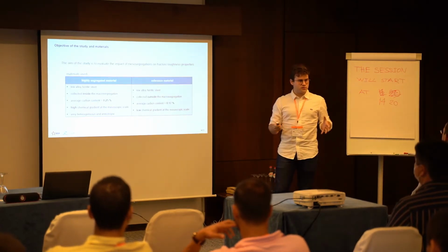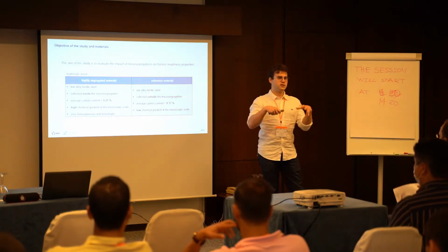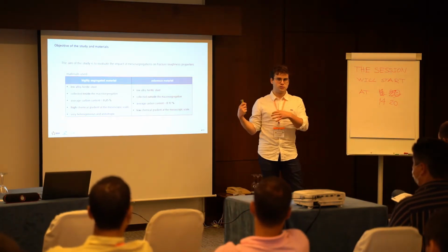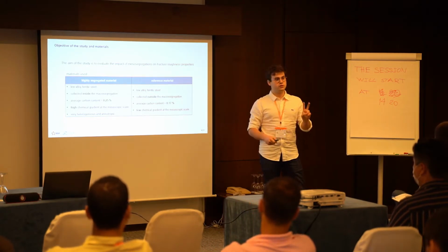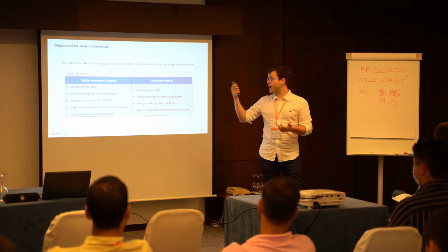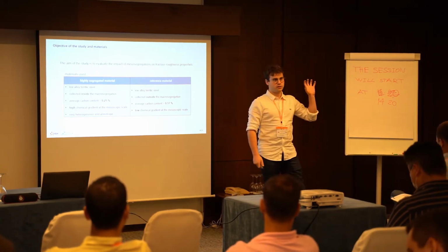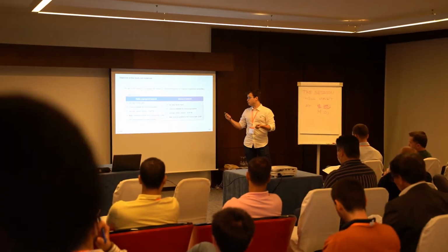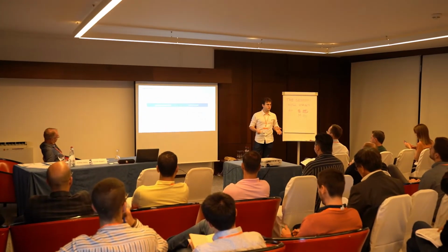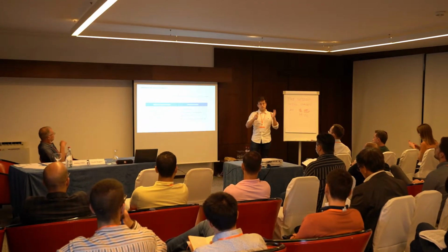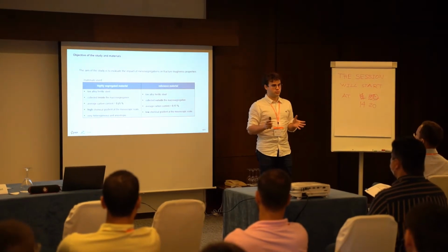So, the aim of this study is to evaluate the effect of those chemical heterogeneities, the meso-segregations, on the fracture toughness properties. For that, we used two different materials. One is highly segregated, collected inside the macro-segregation. Thus, it has a relatively high carbon content, on average 0.25%, and it is highly heterogeneous in chemical composition.